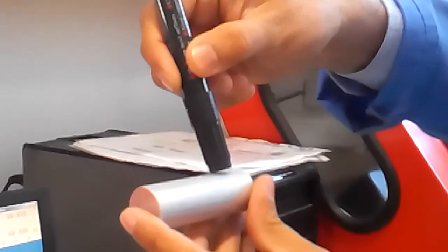Cutting the diameter, we have to bring the tool here and touch it and come outside and cut some diameter in order to know what the diameter is in that position. So in the manual mode we are going to do it. Select the manual mode here, click on X, minus. It is moving very fast, reduce the feed.